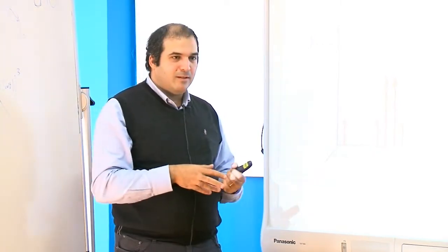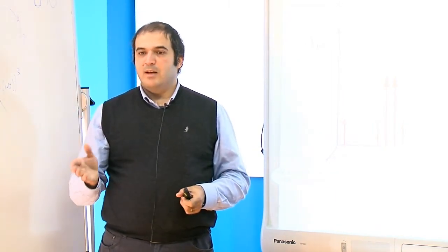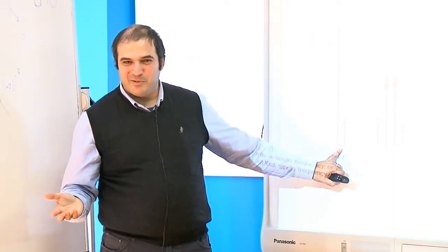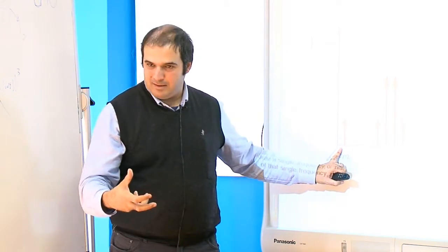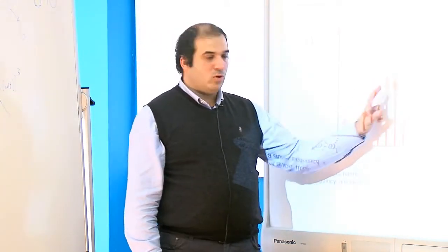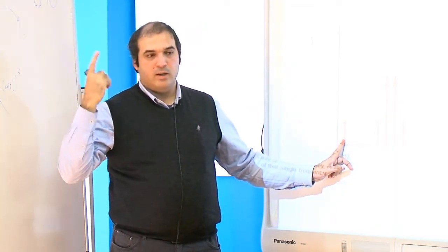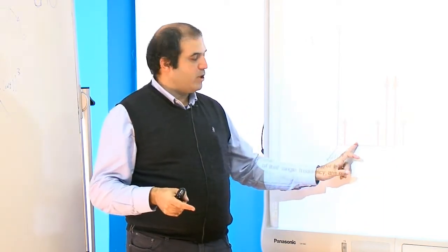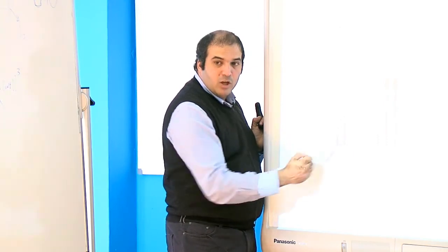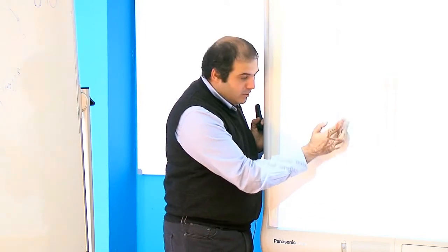Actually, I'm not talking deeply about that, but one phenomenon for power amplifiers is called memory effects. This is the memory, let's say, you can have in your device. This is exciting the memory effects of your device. And what is the problem? The problem is that you use two-tone and you only have one frequency here. Or if you go to higher orders, you'll have harmonics of these ones. But that means you are not exciting the frequencies here, you see? You are only exciting this one.